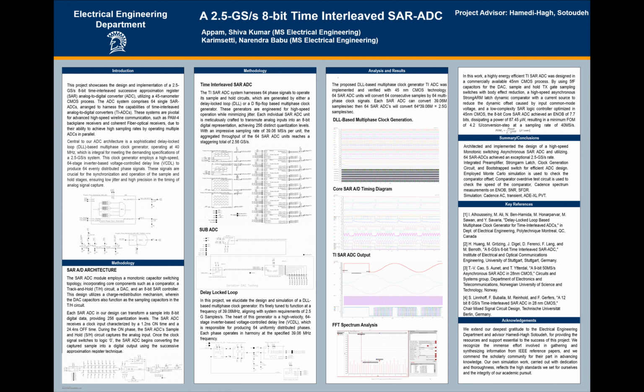So this is our structure. In this time interleaved SAR ADC we built the clock generator circuit entirely ourselves, using the DLL or D flip-flops. First we tested using ideal clock generators, then we tried D flip-flops, then we tried the DLL. Our main intention is implementing the time interleaved SAR ADC using the DLL.